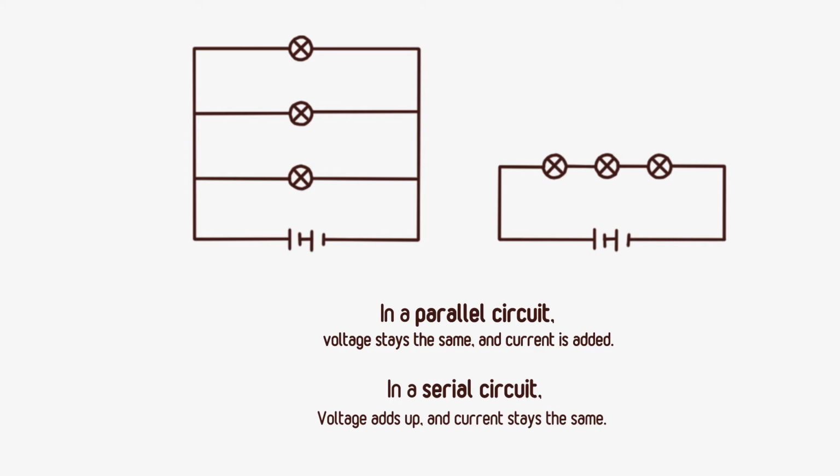In a parallel connection, you do use a lot of wires, but if for some reason, let's just say there's shading on this middle part, you still get electricity through the top panel and the bottom panel. You don't need to worry about one part of your solar panel getting shaded. And there are other benefits, and I'll go into those deeper when we actually get into the installation of our solar panels.